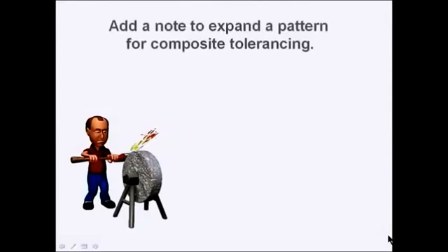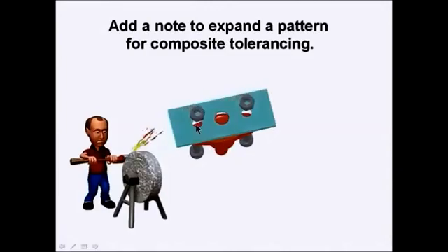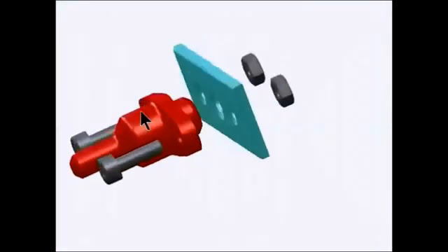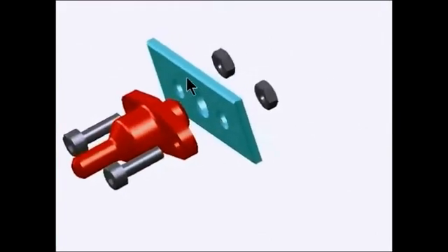Mike Wright, a senior quality engineer for Atom Aircraft, suggested the topic for this month's tip. Here's a tip that should sharpen your geometric tolerancing skills. The title is, Add a note to expand a pattern for composite tolerancing. On this plate, I would like to control these three holes as a pattern. The connector pilots on the larger diameter, and then the two smaller holes are for fasteners.